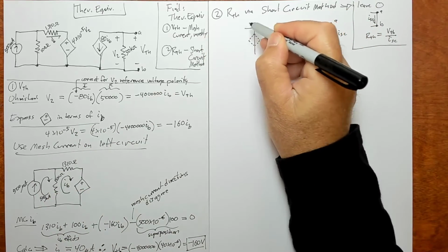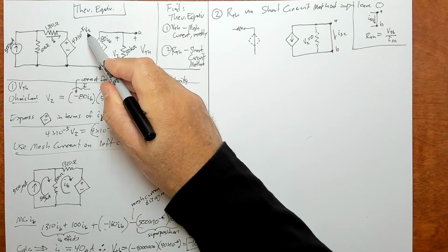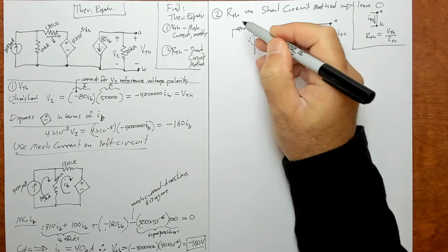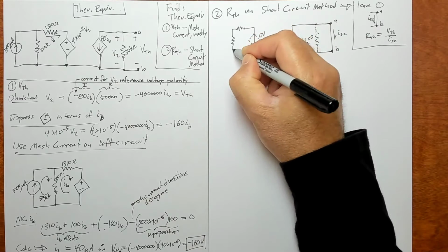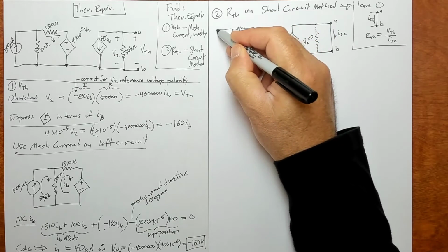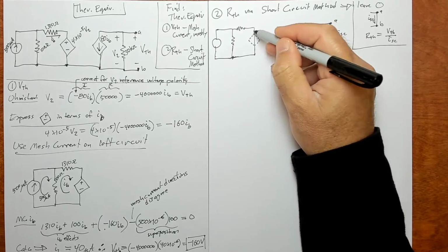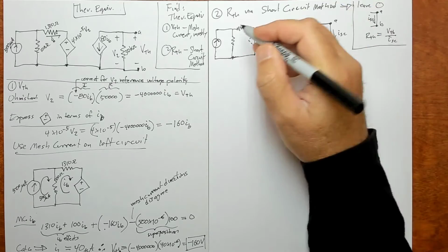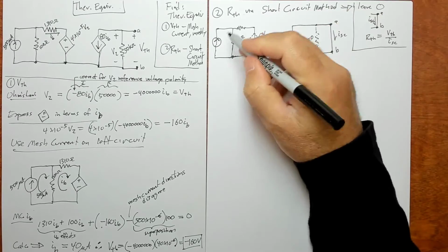So if we do that, then this guy is given by 4 times 10 to the minus 5th times V2. So if V2 is 0, then this thing's putting out 0 volts as well, because it's a dependent source. V2 is 0, you're going to get 0. So the rest of the guys stay in there. They're hanging in there. Just this becoming a 0 volt device doesn't really affect the rest of these guys. They're still there. This is just behaving like it's a wire now,